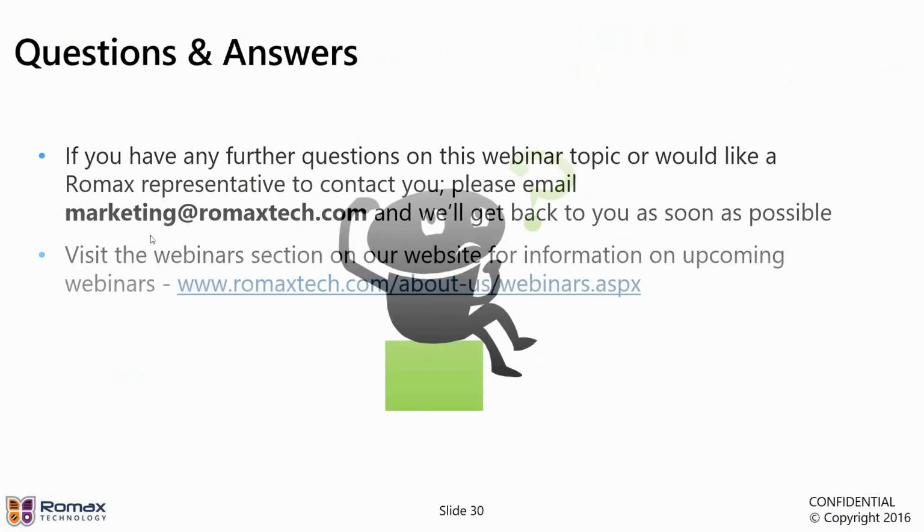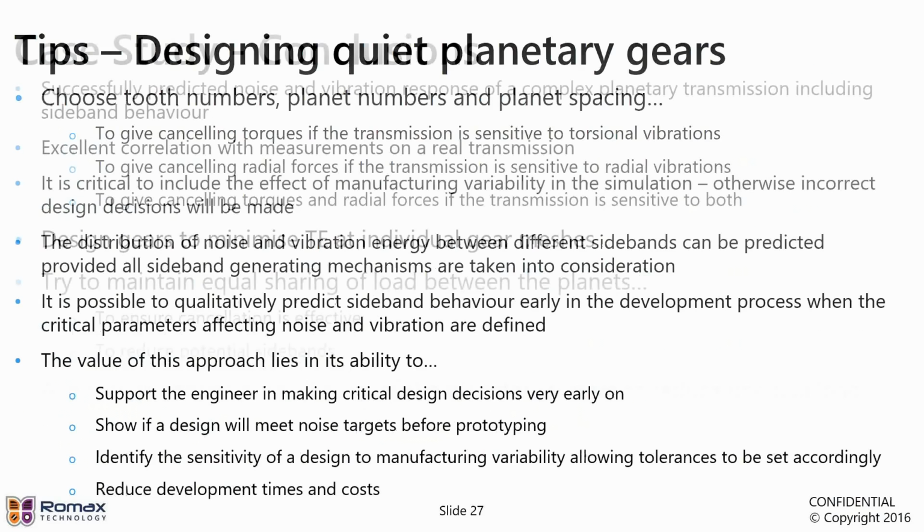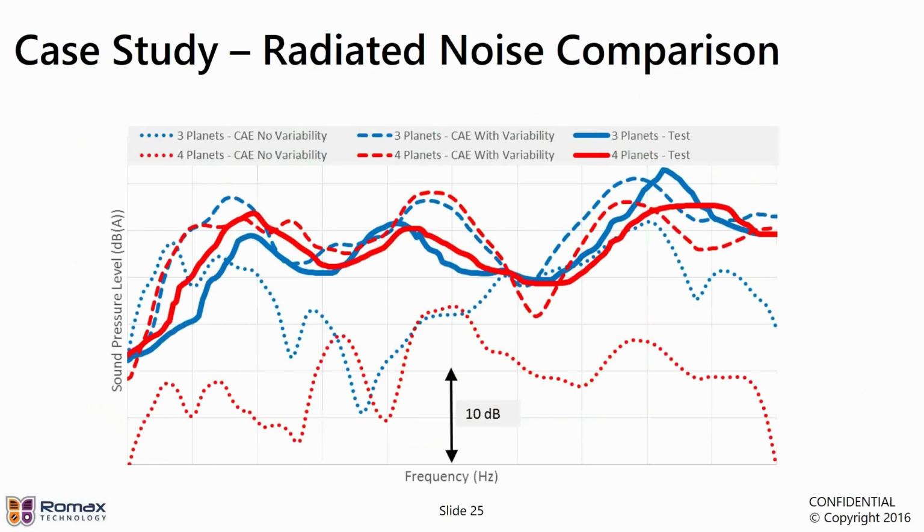So in this case, in particular, we've looked at the pitch errors on the ring gear. Of course, the ring gear being the gear in the planetary gear set that is hardest to accurately manufacture, and based on a sensitivity analysis, those are the ones that showed they had the largest impact. Because this was an existing transmission, we were able to use measured pitch errors from this specific ring gear, but obviously you will have metrology information from your manufacturing processes about typical ring gear pitch error behavior.